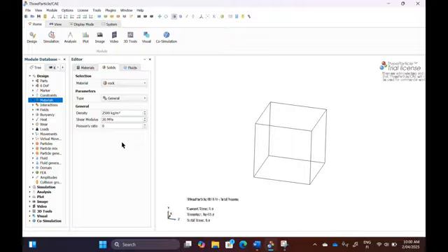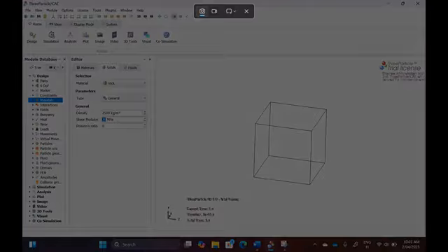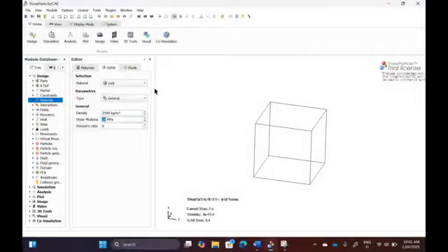Remember last time I painted a sphere penetrating the surface. And it is okay, so it finds a stable state with a small penetration in the surface. The higher this value is, the less overlap is allowed at the mechanical equilibrium. So if you have a very low shear modulus, about 2 or something, the sphere is sinking into the surface. So there is a vertical overlap, and at some point, it's too much.